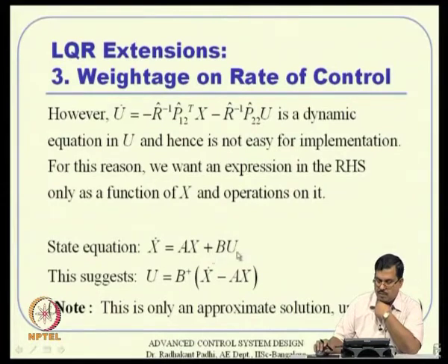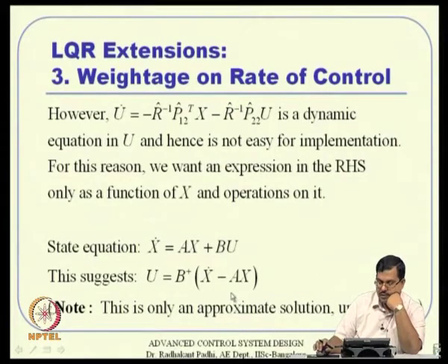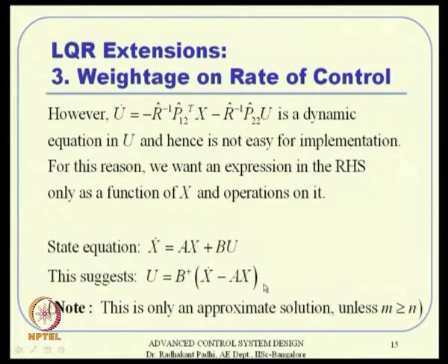We take advantage of this one, the x dot is A x plus B u anyway, we know. So, u turns out to be this solution, where B plus is nothing but the pseudo inverse of B. Remember, this B is not a square matrix in general. So, we cannot talk about B inverse here, and that is where this approximate solution comes in. Anyway, we will not talk too much on that. Here I can solve u from this using the pseudo inverse solution, but because this is an over constrained problem, the pseudo inverse solution is typically not a good solution. That is my own personal comment. So, do not jump into this idea unless it is badly required.